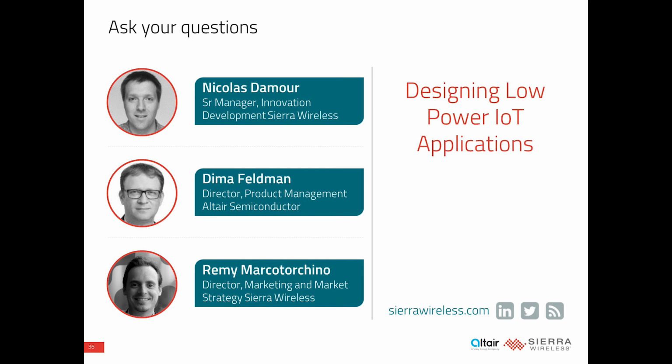So first, I did mention that 2G networks in some geographies are going to be around for some time. So if you don't have a 4G coverage, either LTE-M or narrowband IoT, I will strongly recommend you to look for falling back onto regular 2G. Now, speaking of the compatibility with 5G, it's really a matter of, like I said, the 5G core networks have been designed so that they can integrate LTE-M and narrowband IoT. So nothing will happen to your solutions when 5G is introduced. It will just continue to run, like I said, for at least 1 or 2 decades. So no problem at all there.